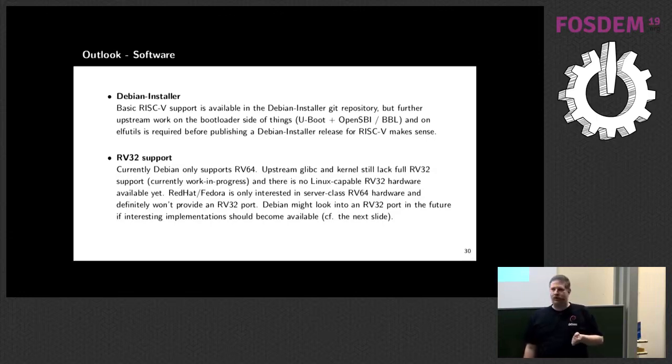Another thing is that we currently don't yet have bootloader support. The U-Boot port for RISC-V is still rather new. Just yesterday, 2 days ago, the first OpenSBI codebase, which we would need for that, has been published. So that's something that I will look into in the next weeks.